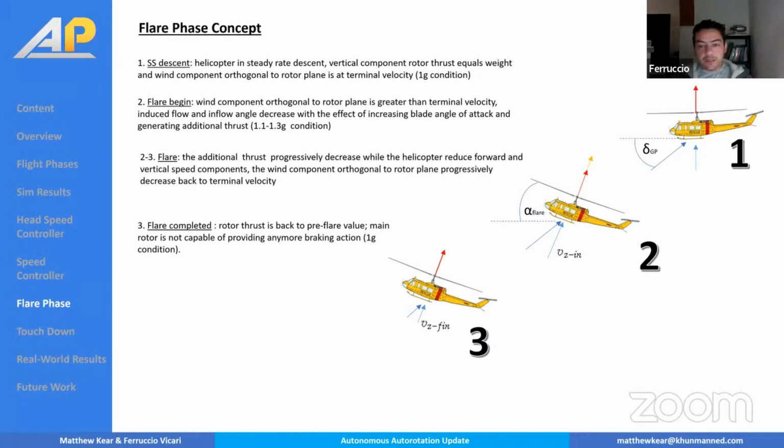What we are using here as a basic idea for the whole calculation is to estimate the relative wind that goes into the rotor, especially looking at the component orthogonal to the rotor disc. And as we can see, this component is primarily responsible for the momentary increase in the rotor thrust, and thus creating a deceleration factor into both the forward speed and the sink rate.